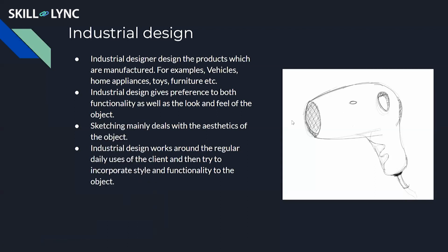Okay, so industrial design, where will it be used that much? The first example is vehicles. The vehicles should look very neat, very good. In their case, industrial design comes into the picture, and the development of a vehicle will take place this way. First you do the sketch, and then you build a class A surfacing model of it using software tools like Alias, ICEM Surf, or sometimes CATIA. Then you take the surface as a reference and create an actual geometrical model, which we call a clay model, right?